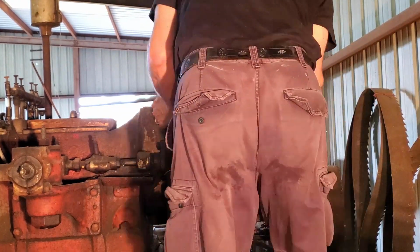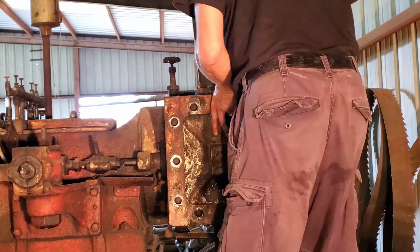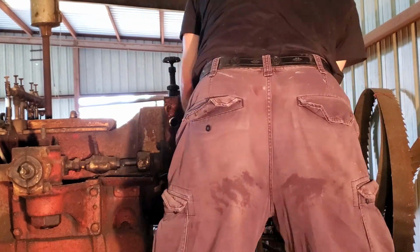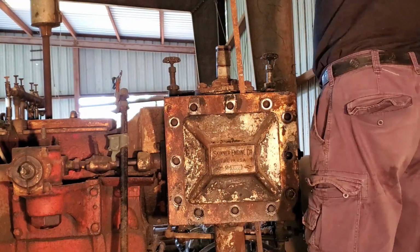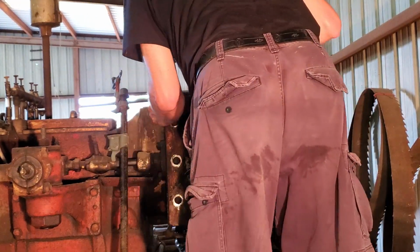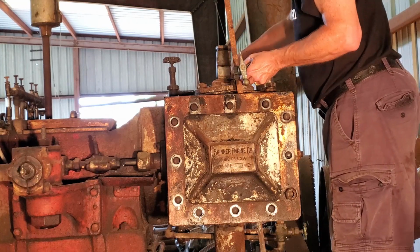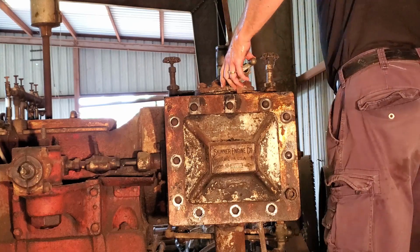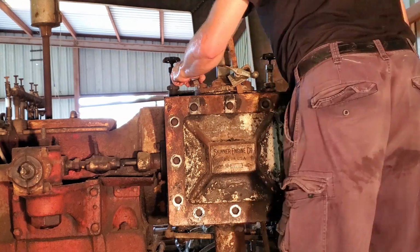Now at this point, what I need to do is get a piece of flat bar slid in behind the face of the steam chest cover to act as a stop to prevent the slide valve and balance piston from falling when I remove the steam chest cover. So I'm trying to rig up a bar clamp behind it. And yeah, we won't even talk about that. Just trying to get the steam chest cover to move off of the bolts. And once I get all this rigged up, which only has to last for a few seconds, we'll be able to pull that 100-pound steam chest cover off.